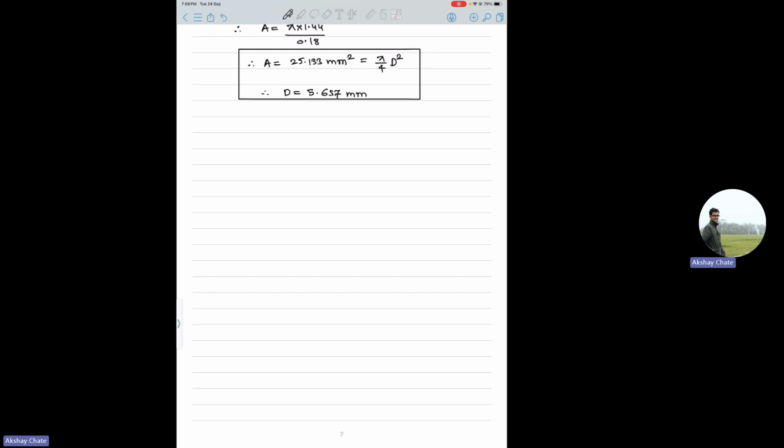Okay, so what happens? The solubility of a particular alloy element in the liquid of the other metal is different than in the solid. Okay, so that is why it's very difficult. Plus, there are certain effects like Marangoni convection, radiation heat transfer from the melting pool to the surroundings,